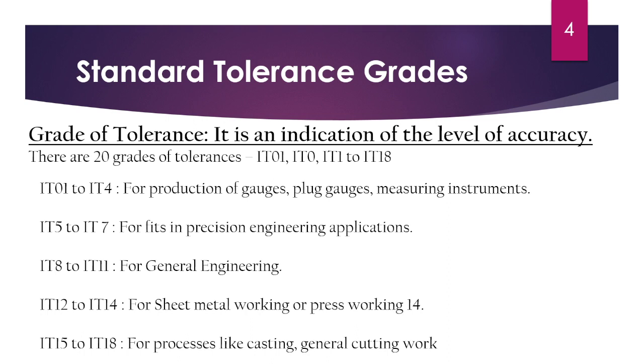Standard tolerance grades. The grade of tolerance is an indication of the level of accuracy. We have 20 standard levels or grades of accuracy from IT01 to IT18.